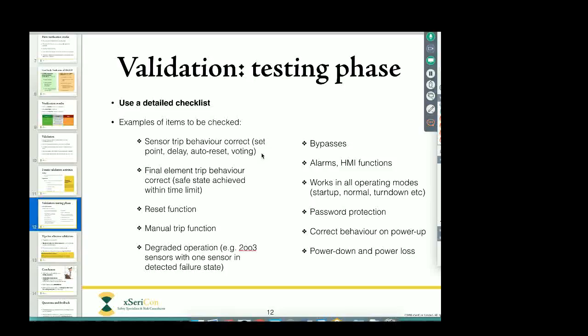To test all of the combinations will probably have been done already during the FAT, at least from the software and the I/O card point of view. So there's probably no need to test exhaustively every single combination with the field equipment. Though of course the more you can do, the sounder the check will actually be.